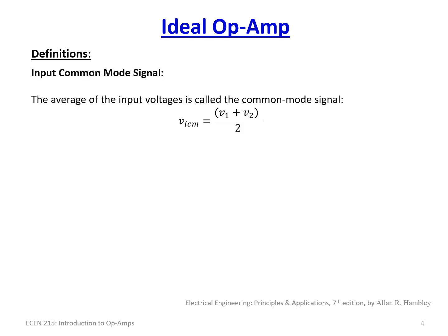First, there's the input common mode signal. This is the average of the input signals and is known as the common mode. Basically it's the average of V1 plus V2. Think of it this way: if I had two signals, both centered at 0 volts, say we're injecting AC signals into the amplifier, and both of them were centered around DC at 0 volts, then you would have 0 plus 0 divided by 2, which would be 0 volts. That's called the common mode signal.